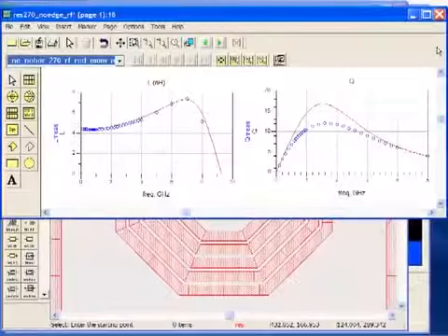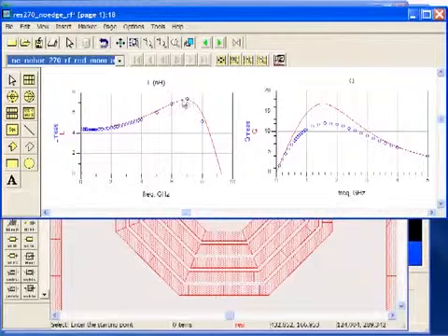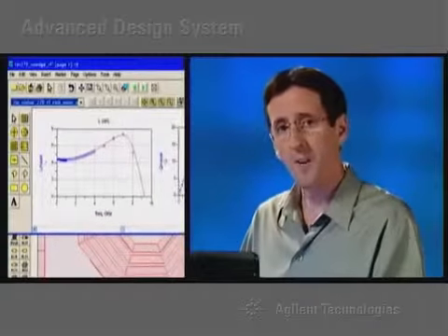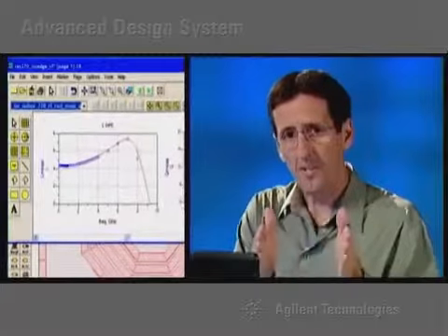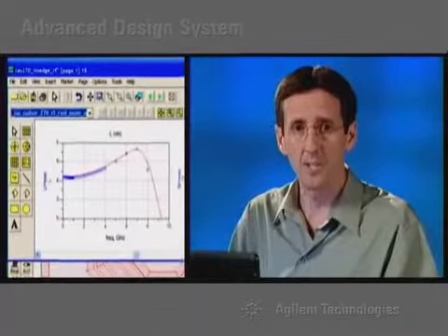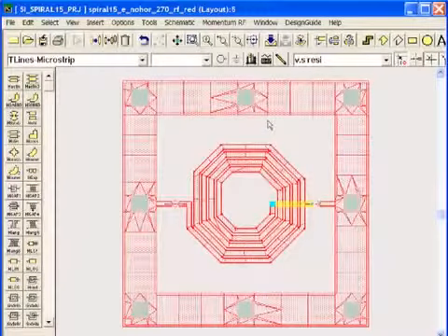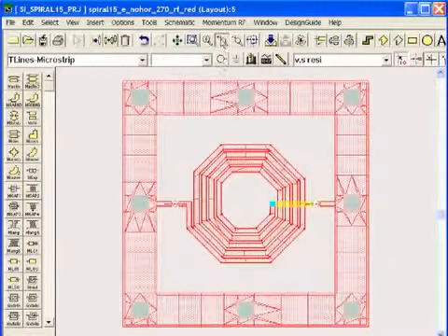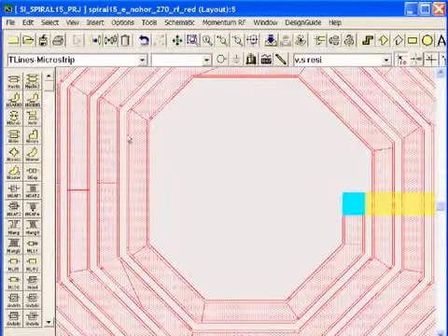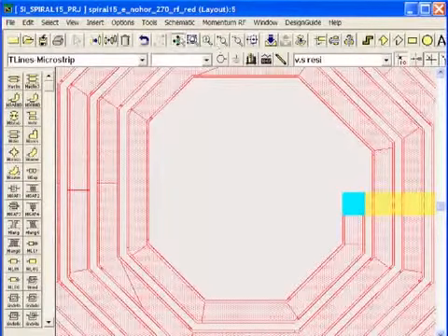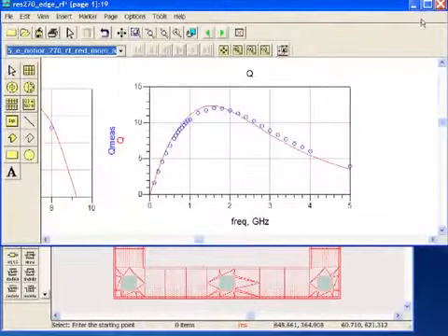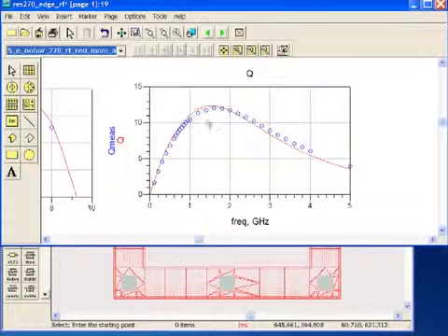You can see the results for the inductance compared to measurements are reasonable, but the results for Q are less accurate. Since most of the current is at the edges of the traces in this inductor, we used edge mesh in a second simulation. With edge mesh on, we get a mesh that will do a better job of capturing the current distribution in the conductor, but this more complex mesh causes the simulation to take 8 minutes and 15 seconds. However, you can see the results for Q are much more accurate.